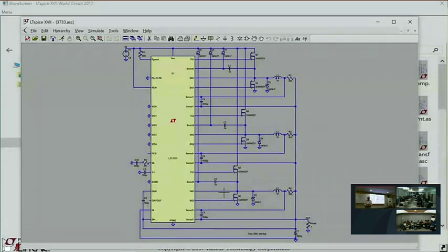And then you'll have no current going through your output filter capacitor, so there's nothing flowing through its ESR dissipating power, and you have nothing read out to a voltage. That's a polyphase switcher. Now this part here, each IC will control three phases, but you can daisy chain these things with PLLs and all that and run lots more phases. But just to look at one of these polyphase switchers, there's three phases, so there's three inductors, there's three current sense resistors. Each current sense resistor voltage has to be hooked up to the right current sense amp.